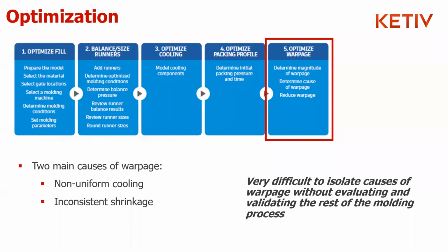That's a good point. In regards to adding detail, that avalanche of detail I mentioned earlier, if upfront you certainly can make some assumptions and see geometry effects with, say, ideal cooling, uniform mold temperature, but you might miss something. And shrinkage is quite complex through thickness, region to region, and even orientation effects can sometimes be identified early on, but until you expose it to a bad runner design or an inefficient cooling design, that upfront work really didn't help if you still made a mistake later on in the phase. So great point on that. Yep, agreed.